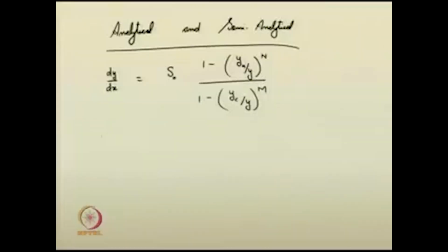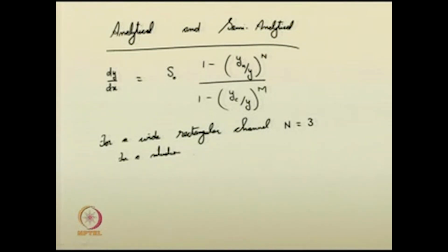For a simple case, for a wide rectangular channel, using those relationships, it is observed that your hydraulic exponent n is equal to 3. Now, for a situation where n is equal to m is equal to 3, if you take this thing and if you had used